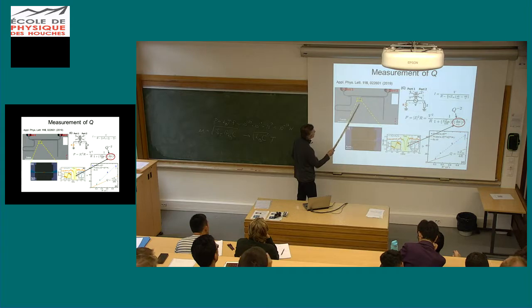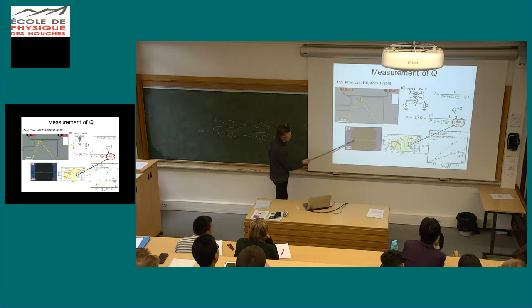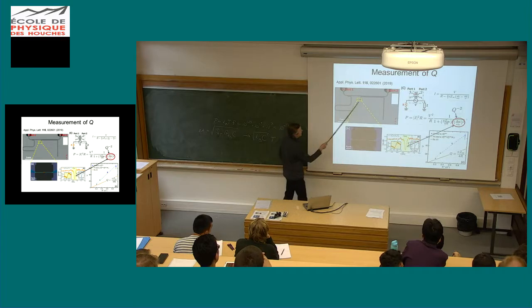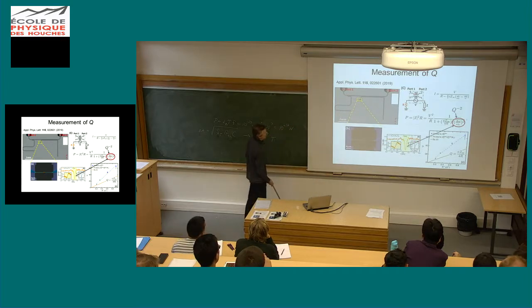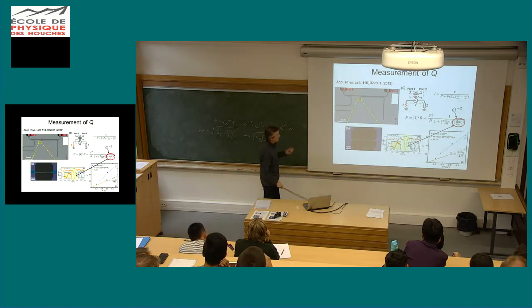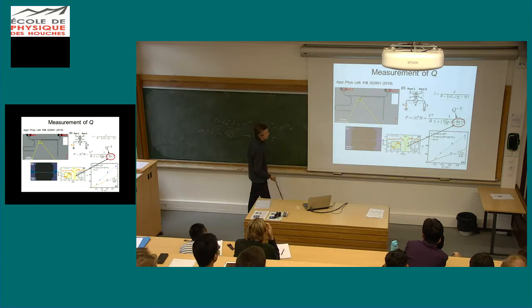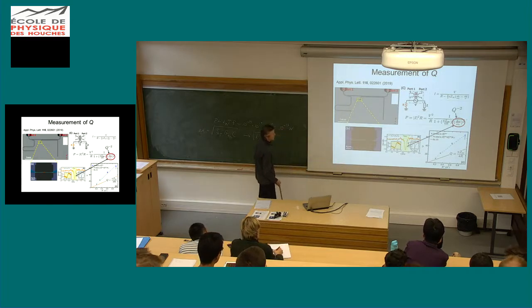But what we did was that we added this kind of an absorber that I've been talking to you about, a few micrometers long resistor, at the end of this resonator, and we had a reference resonator which did not have it. If you don't put any such resistor at the end, your typical quality factors are of the order of tens of thousands, but now indeed this resistance gives you a much lower quality factor.